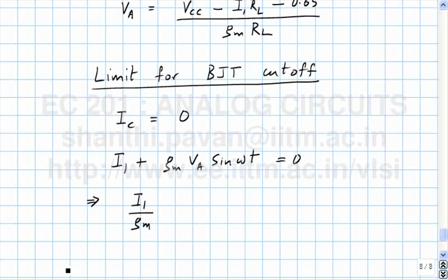Vt. And please note that again here we are making the approximation that the total current is basically the sum of the incremental current plus the quiescent current even for large signal operation. Okay? And this analysis is telling you that if the VA is Vt, the collector current of the transistor will go to 0. In reality, what happens?